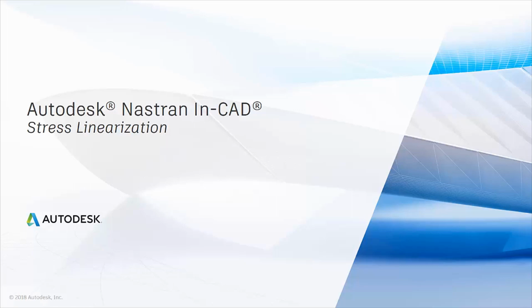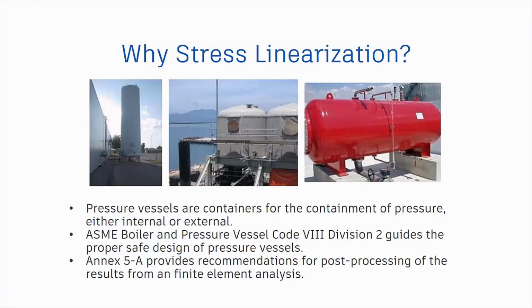Welcome to this quick tip presentation about stress linearization using Autodesk Nastran In-CAD. Stress linearization is typically leveraged when you perform finite element analysis of pressure vessels in accordance with ASME Boiler and Pressure Vessel Code Section 8 Division 2.